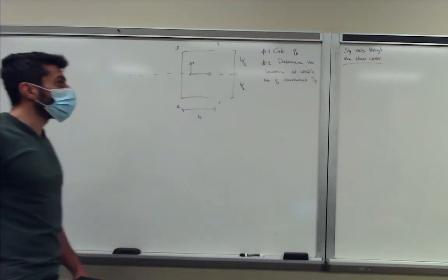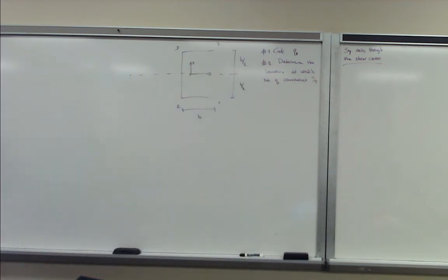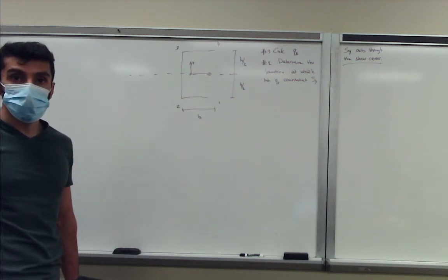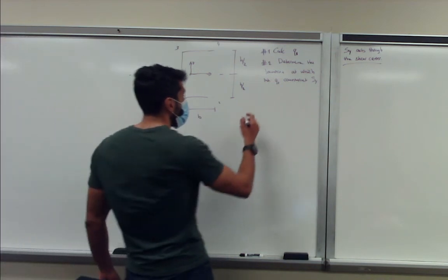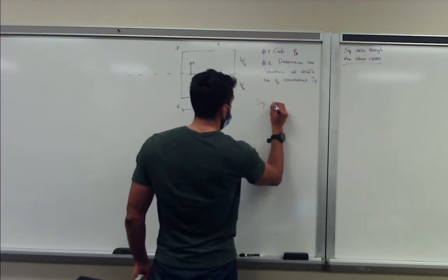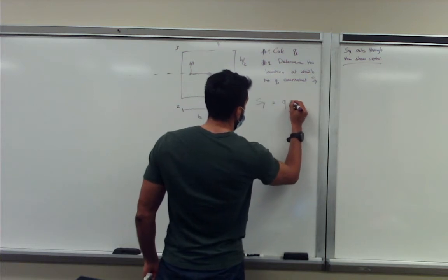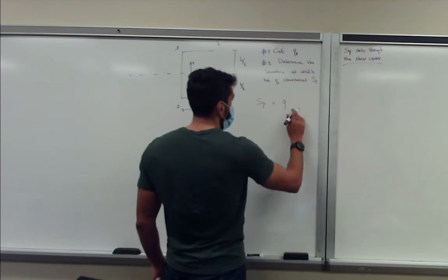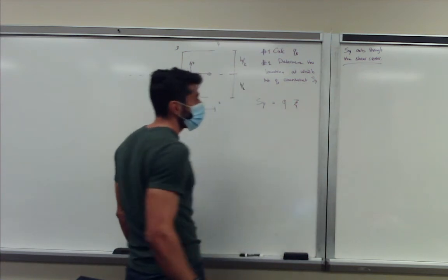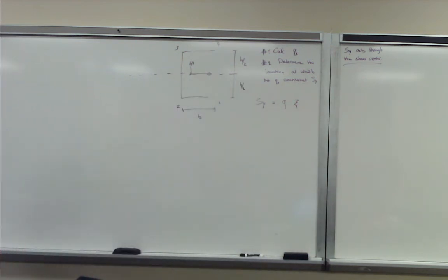We have to determine the location of the internal shear flows counteracting the external shear force. So we do a moment equation. We say that Sy must equal Qs multiplied by a certain arm E, and in most cases we will use the Greek letter psi for that.